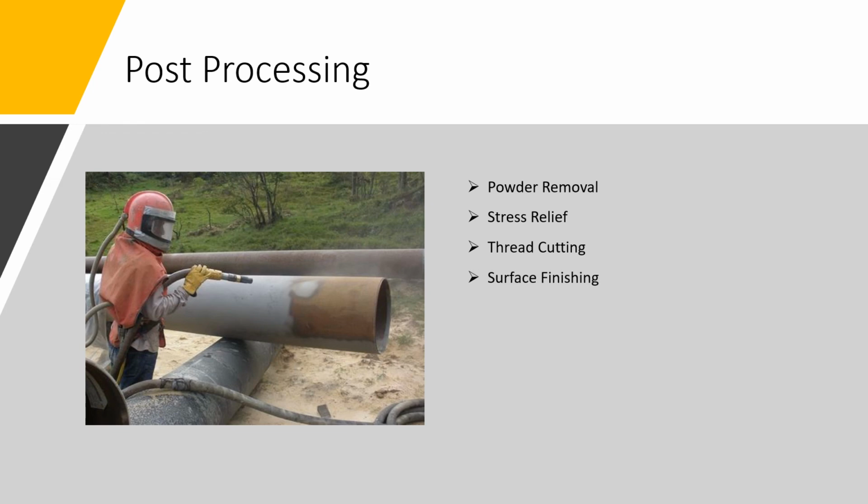To improve on surface finish, the manifold should have the external features subjected to a light sandblast to reduce the appearance of layers. Internal bores should be lightly polished to improve surface finish. The manifold should then be anodized to further enhance the cosmetic appeal and to further increase the corrosion resistance.